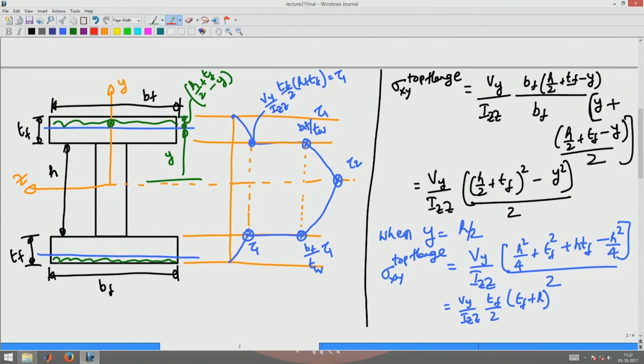Okay. On the other hand, if I had a very thin walled section like hot rolled steel sections for I section, then the flange thickness will be like 10 mm or 12 mm or 20 mm at most. In those cases it cannot resist this tau 1. Okay. So, there should be a different mechanism by which equilibrium is satisfied by the sections.